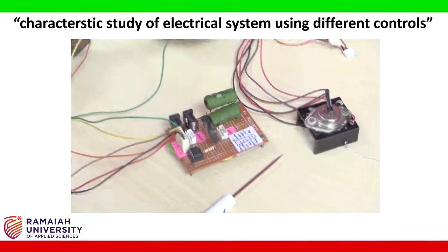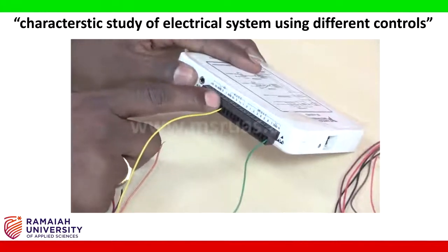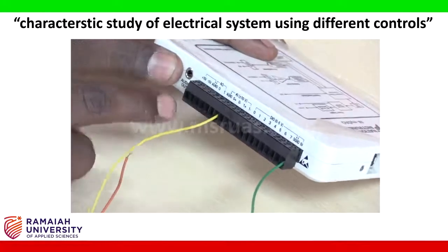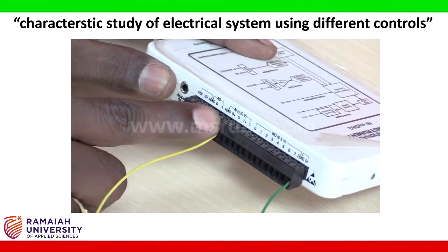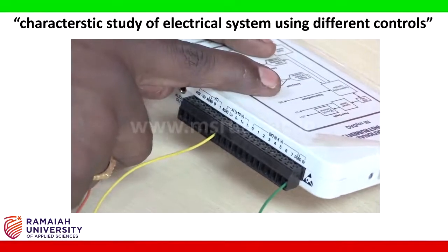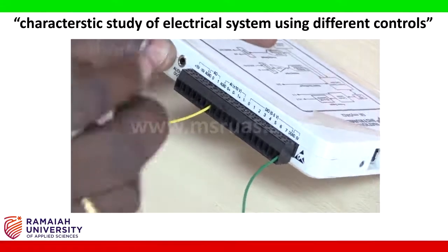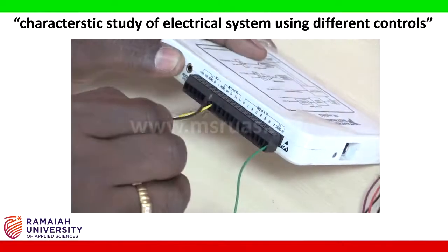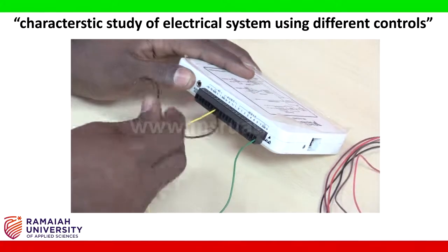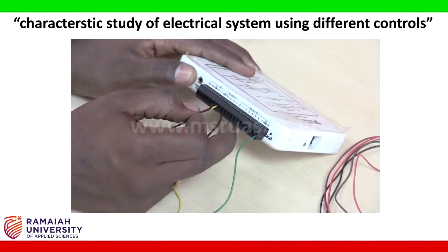And since the analog input channel has two terminals, 0 plus and 0 minus, and whatever terminals we are interfacing will be interfaced to an instrumentation amplifier, the 0 minus has to be connected to ground. So we are taking an extra wire and connecting 0 minus to ground.